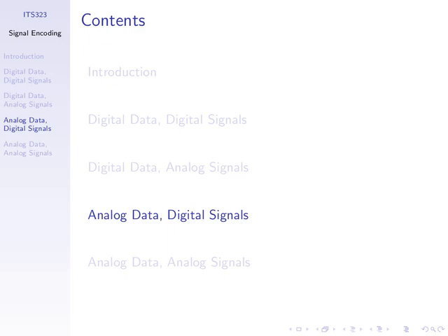If we have digital data, zeros and ones, but we need to transmit analog signals, then what we do is vary our simple sinusoid signal based on one of those three variables: amplitude, frequency, and phase. If you remember back to our simple sinusoid equation, there are three parameters that we can change. If we want to transmit a bit 0, use a low amplitude of our sine wave. If I want to transmit bit 1, use a high amplitude of the sine wave. And similar with frequency and phase. So they were amplitude shift keying, phase shift keying, and frequency shift keying. And in fact, they can be combined together.